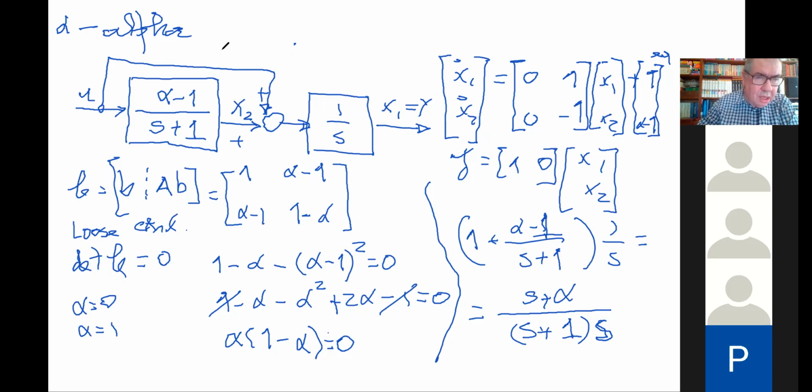So in general, I call it the controllability matrix: B, then AB, then A squared B, up to A to the n minus 1 times B. Now, in this case, the system is of order 2. So n is 2, so n minus 1 is 1. So you stop at AB. You just have the first two terms. And the rank of this matrix must be equal to n.